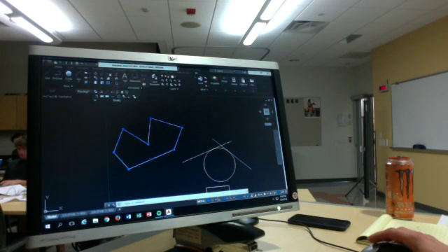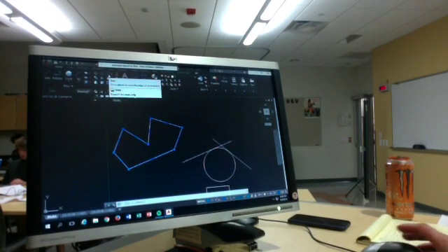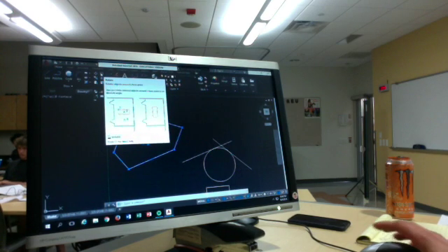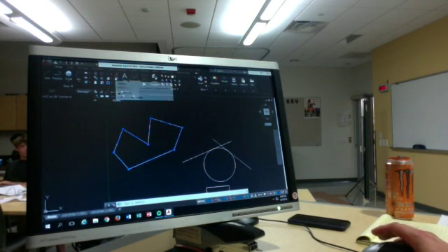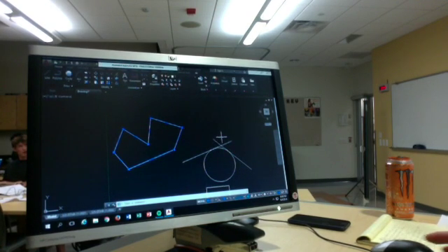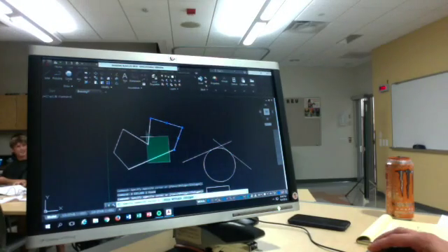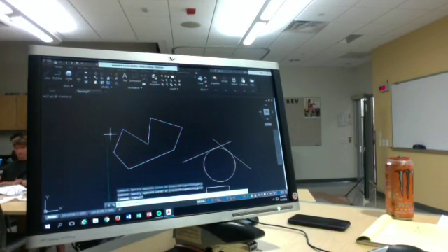That's erase. Trim, rotate. Oh yeah, that's what it was. Delete. The keyboard shortcut is just E when you have something selected. Yeah, so you can click on explode, or if you're in the object, you type X and hit enter. Now it is 7 different objects that you're looking at.